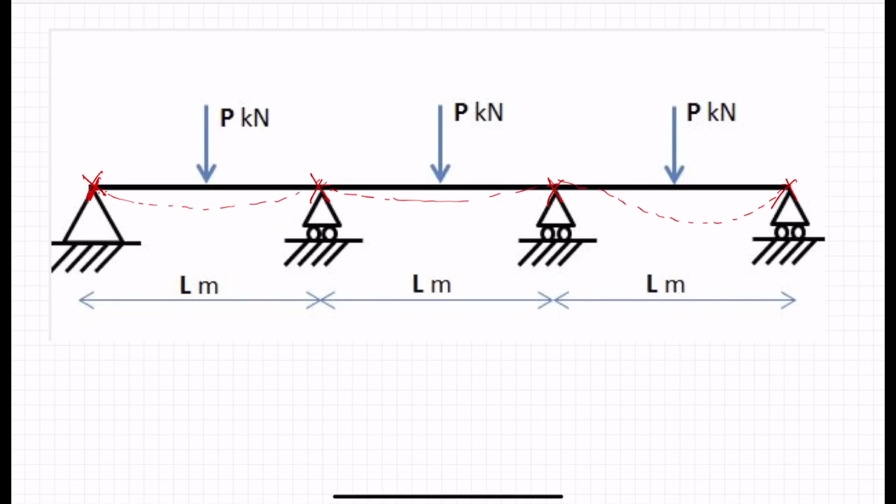But the key question here is: is the magnitude of the deflection in the center beam less or more than the outer beams? And the answer is less, because the outer beams are causing the inside span to push up. So why is that important? It's because now when we try to draw the bending moment diagrams, let's use a thicker blue. Bear in mind these are all vertical reactions. This is a symmetrical structure as well, so these are all equal to each other.